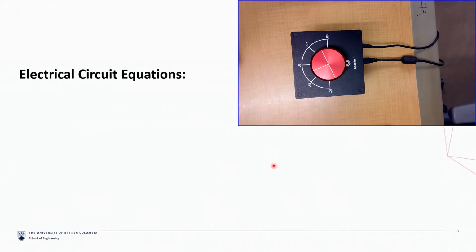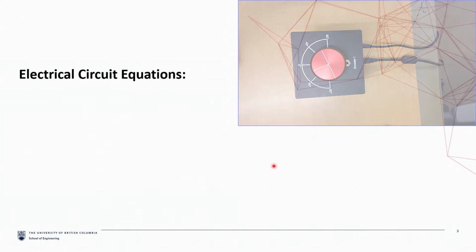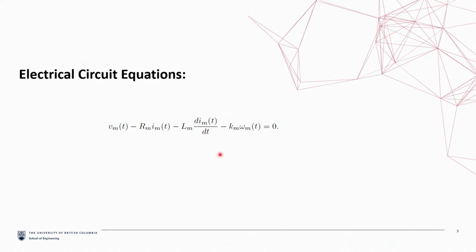All these components are rigidly connected to each other and rotate around the same axis. Next, using Kirchhoff's voltage law, we can write this equation, and we can simplify this equation knowing that the motor inductance has a relatively small value. And next we can again rearrange this equation for IM and specify the driving current of the motor as a function of the angular velocity and the voltage.